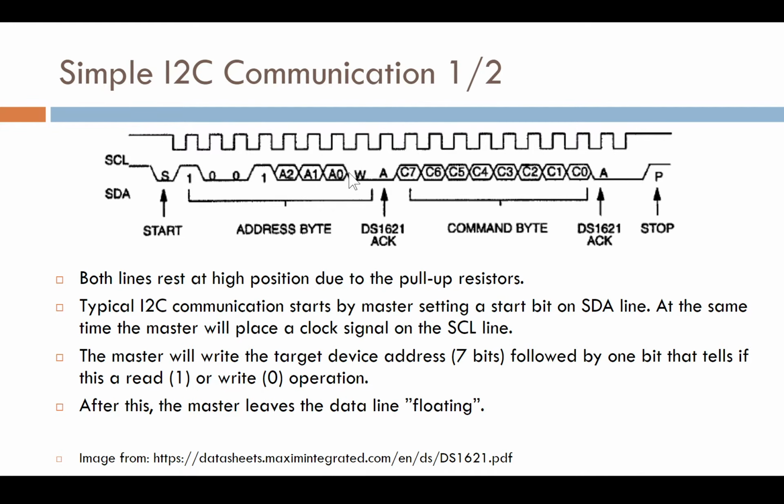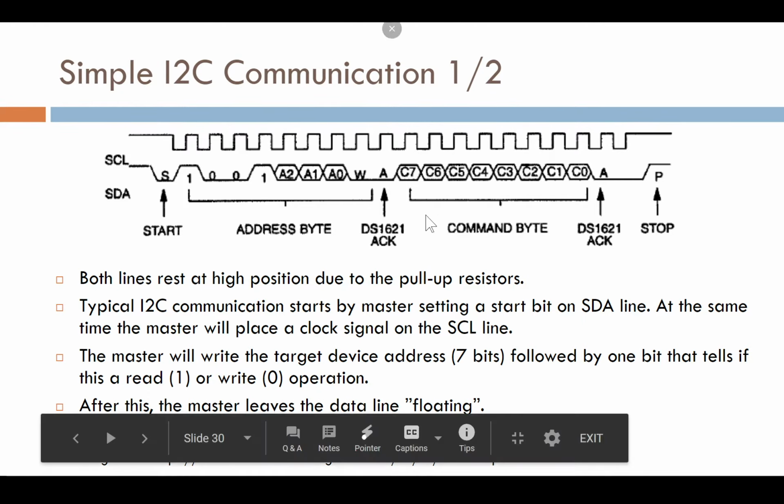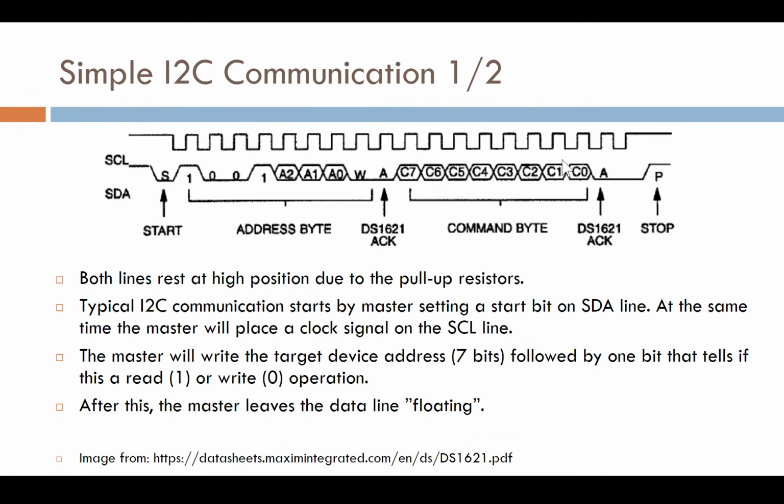If that is a read bit, then on the next byte that device, which recognizes the address, will start reading stuff, start setting stuff on the line. Okay. And after that, in this case, it was a write and a command byte.